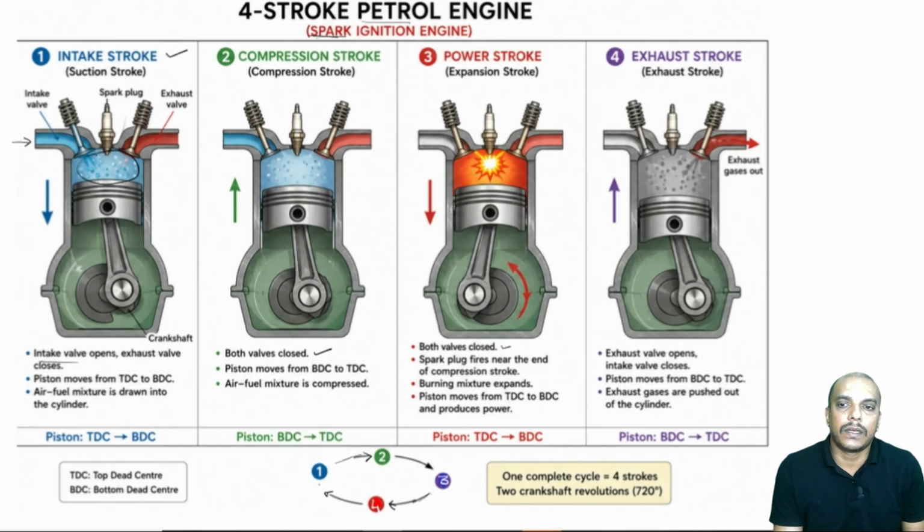And remember, this rotation for a 4-stroke engine, for each stroke, that is for the suction stroke this will rotate 180 degrees, for the compression stroke this will come back here, so 180 degrees. Okay. So, for each stroke the rotation will be half. Therefore, the total rotation for a 4-stroke engine will be 720 degrees. So, 180 plus 180, 360 and 360 here. So, for every 2 rotations, we will have 1 power stroke.